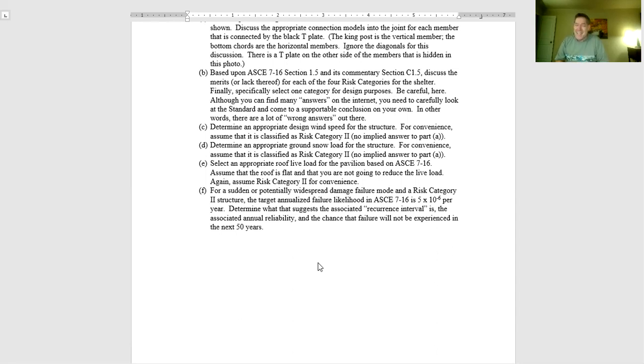That's what they say. So like we talked about in class, you go to the USU snow load map in their web browser, and they'll again put in the address. You'll get back 31 pounds per square foot. If you go to the current Salt Lake City design guide, they'll tell you that the minimum is 28, but then what you've got to do is go to the Utah snow load, and you'll find out that 31 is the appropriate one to use. All right, so that's the current 2018 based criteria from the city.